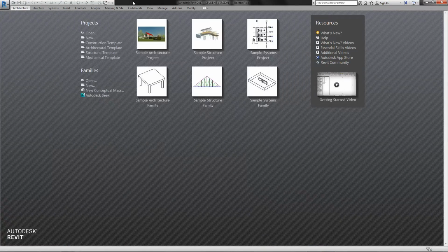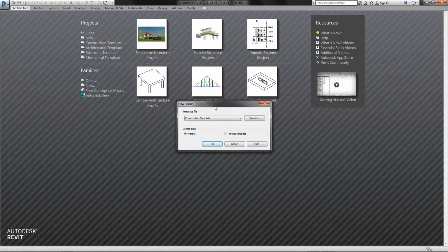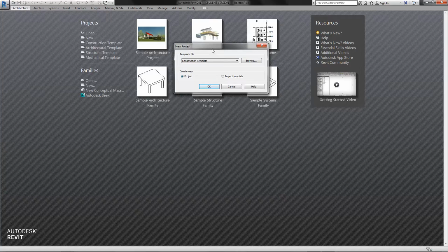All right, so when you open Revit, it will look like that. So installation, everything is very simple. You just do it through your education Autodesk, and then you will install Revit 2017, and you'll see an interface like that. So if you don't have a project yet, you'll say new. If you have a project, you'll open it. So when you say new, it'll ask you what kind of work you gotta do. So you'll pick a template as everything else may ask you. So for this, I'm gonna say architectural template, and I'll say okay.